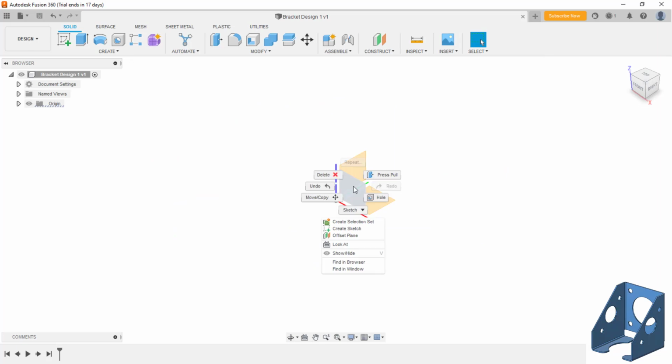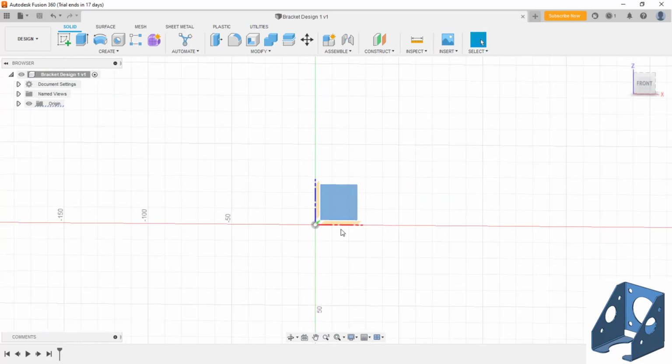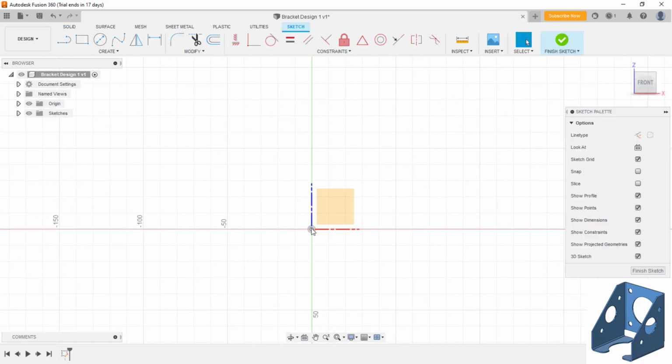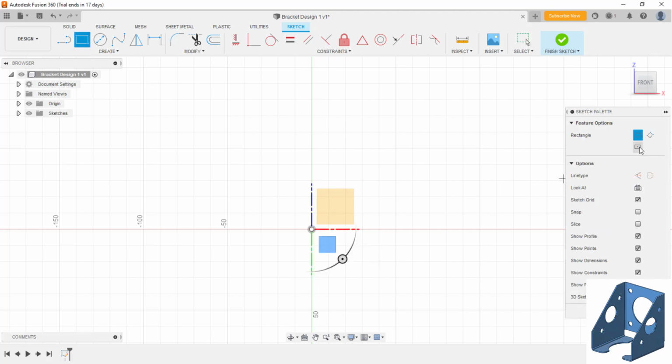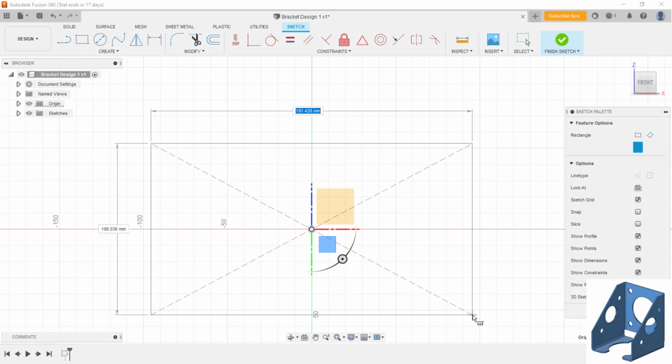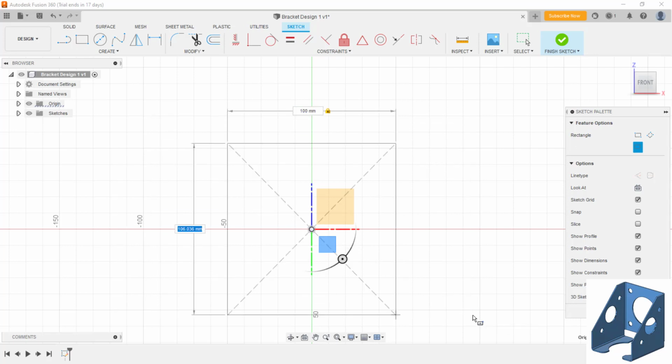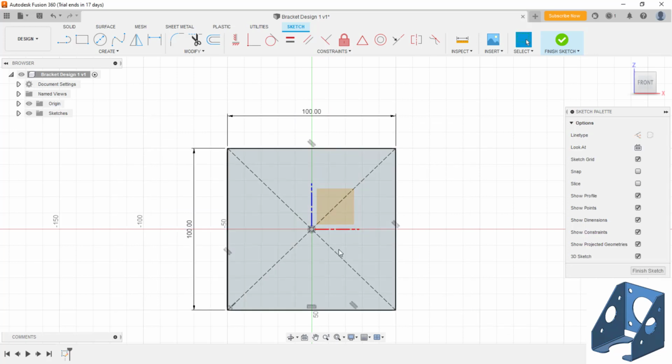So we'll see the model design now. You can start with create sketch, right click and just use a shortcut. Here I'll try to draw the front face of this particular model, which you can see at your right corner. I'll use the S key to activate the rectangle. I'll use the center rectangle instead of the corner rectangle, so I can directly input the values. So 100 by 100, I'll take the values.